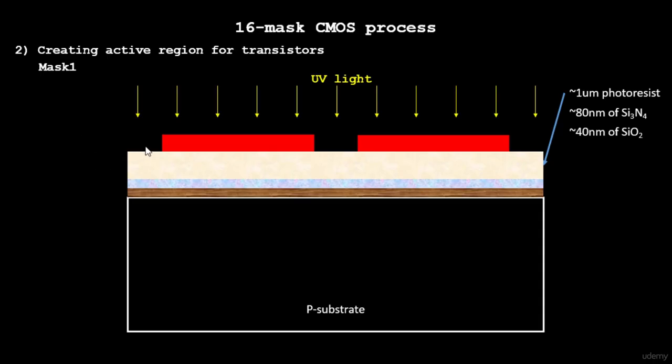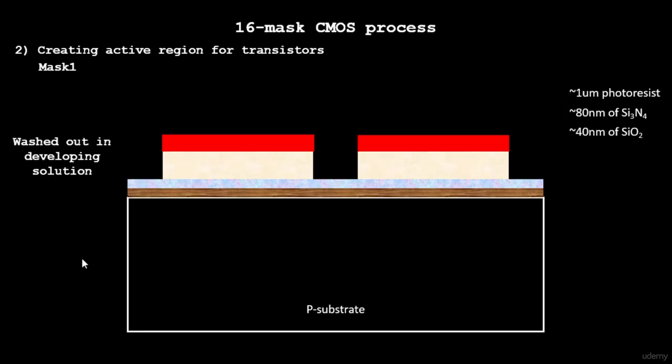There are various kinds of substrates available, but we'll go for the most common one, which we use for most of your mobile devices or any kind of chips that you see in real time. So we'll go for a p-type silicon substrate. It will have some different properties, and some of them are high resistivity, or the resistivity property of the substrate, and the doping level. Doping is the process of adding a foreign impurity into a p-type substrate. Something which comes as a foreign material is called doping. That's why the name doping has been put over here.